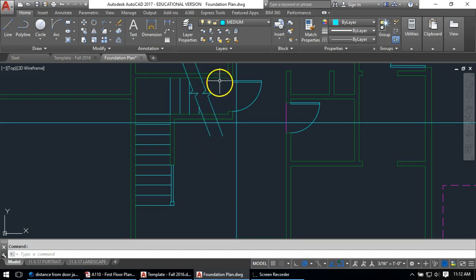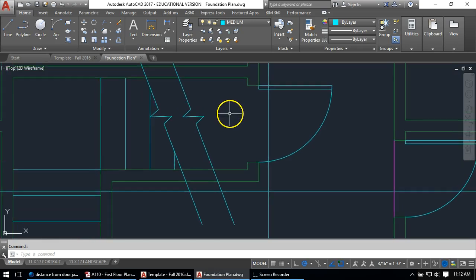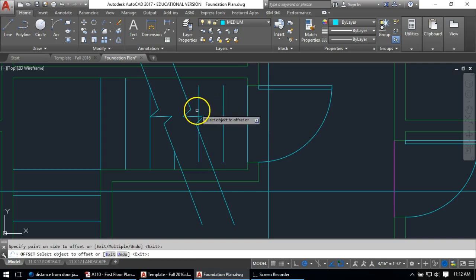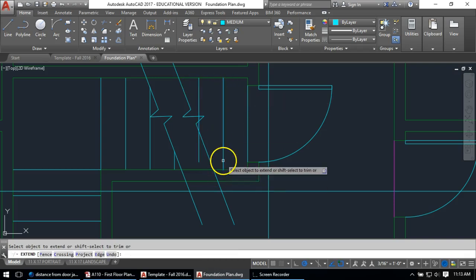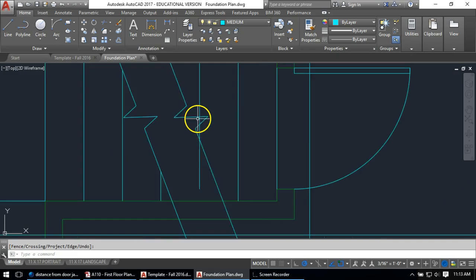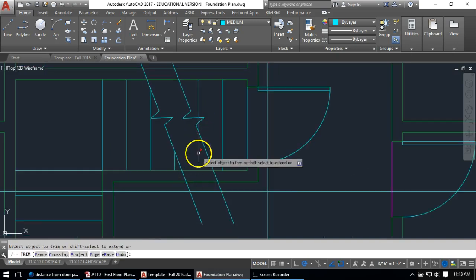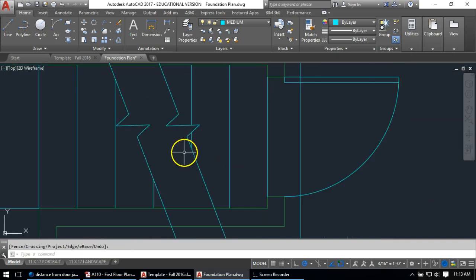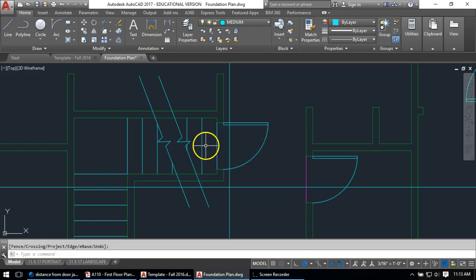This is how you show a gap. And then I need to show the stairs as they are coming down. Usually there's a stair somewhere around the entrance, like in that location. So I'm going to mark that as the edge of the stair. I'm going to offset 10 inches and 10 inches because that's what each of my stairs are, and just sort of clean this up to make this go to edge there. But this stair needs to be trimmed out around the brake line. So I'm going to trim there and even there. So this is my stairs down to the basement.